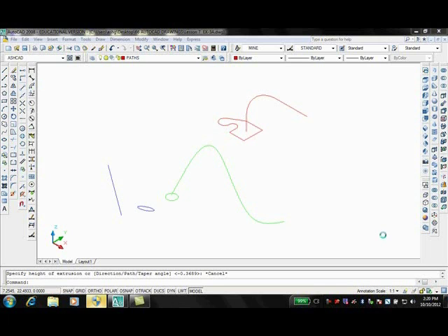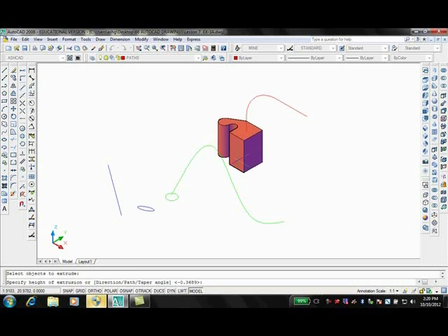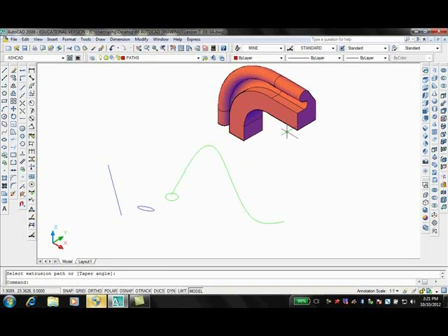First, I will extrude the red profile on the right. After extrude is entered, I'll select P to indicate that I want to extrude along a path and pick anywhere on the red polyline. You'll notice that the profile was extruded along that path.